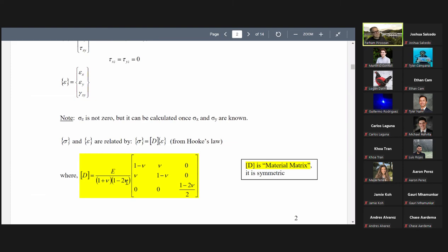Poisson's ratio of 0.5 means that if you apply pressure on all sides of, let's say, a cube, the material will expand. But that's not possible: when you apply a compressive stress on a stress element like a cube, the material shrinks, like the volume dilatation that you had in your strength of materials. Poisson's ratio of 0.5 means the material expands, so physically it's not possible.